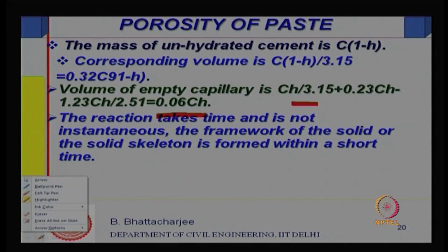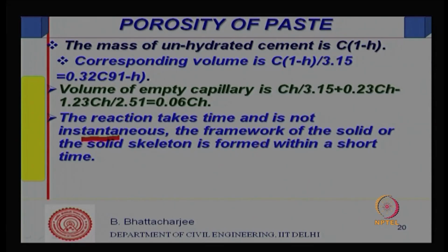Now, the reaction takes place, it takes time, it is not instantaneous, but the framework of the solid is formed quite quickly. So, within half an hour, initial set. The framework forms pretty quickly, you can't disturb it any further.